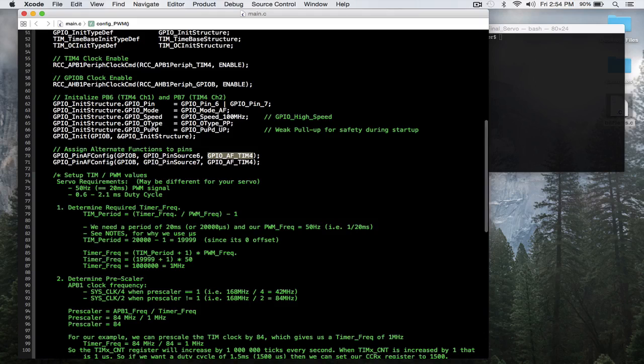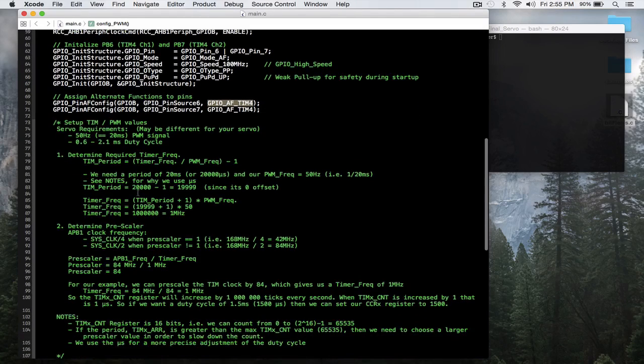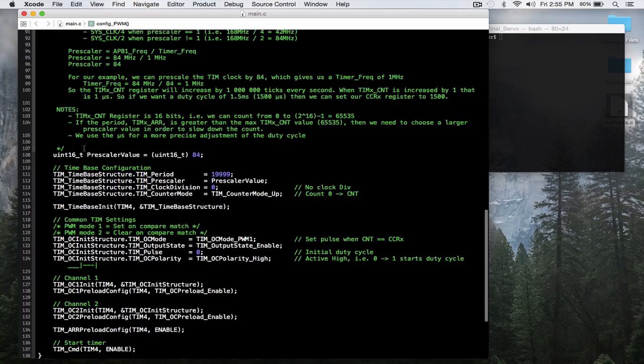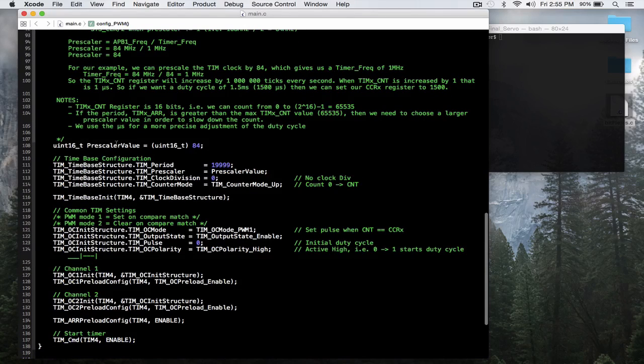Now we need to start configuring the TIM and PWM values. I have a whole bunch of notes here that you can read through on your own, but it's essentially what I went through at the beginning of this video. Now you can see here we declared a prescaler value, and as we found at the beginning of the video, we're going to set it to 84.